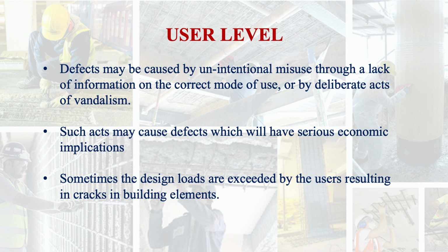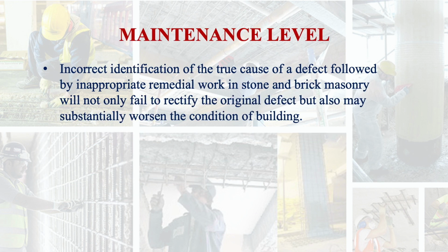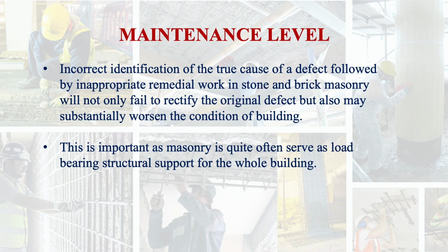Sometimes the design loads are exceeded by the users, resulting in cracks in the building elements. This is also there. Then finally the maintenance level. Incorrect identification of the true cause of a defect followed by inappropriate remedial work in stone and brick masonry will not only fail to rectify the original defect but also may substantially worsen the condition of the building. This is important as masonries quite often serve as load-bearing structural support for the whole building.